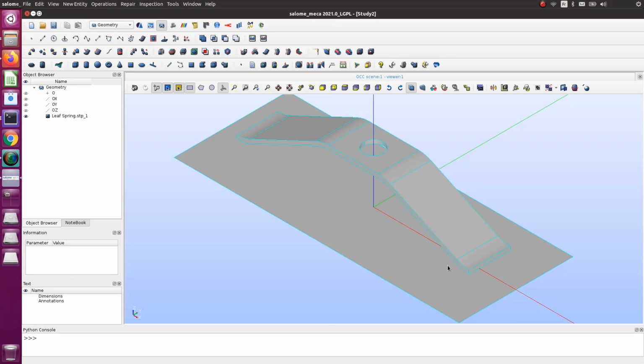So the way to start is to say, okay, I will start with something very simple. Only the spring, so I will remove the contacts, and I will also remove the large deformation nonlinearity and the elastoplastic material, and I will only run that as an elastic material, which is basically just a spring fixed on one part. So this is the first step of the simulation, and this should be very simple to do if you know how to use Code_Aster.